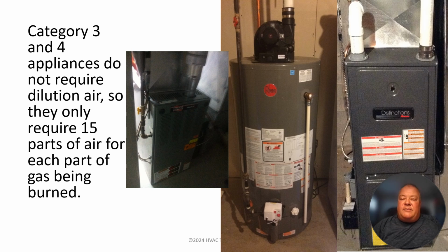And we've even got a high efficiency furnace in the example on the right there, but what I want you to notice is that the intake pipe doesn't have a dedicated pipe heading outside. It basically is cut off and just sitting collecting the air from the room around the furnace itself. So while all three of these do not need nearly as much air as their old natural draft cousin, they still need half as much air.